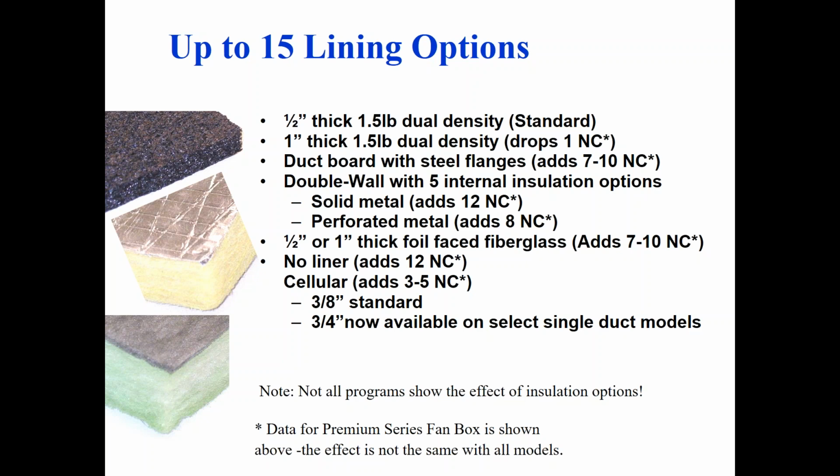You could get no liner if you didn't want one. It's going to cost you more. It's a premium to not get the liner, and it's going to be a massive sound penalty. Fiberglass is really good at absorbing sound, which is why if you ever do a project for a recording studio or a theater, they will have panels on the wall made of absorbent material like fiberglass, so the sound waves can go in there, get trapped, bounce around and neutralize themselves. So the 1/2 inch thick liner is there for condensation purposes and for sound purposes.